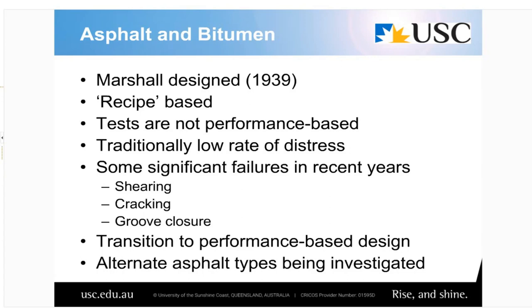It's important, I think, to understand that those shearing, cracking and groove closure issues are very complicated and we don't absolutely understand what's triggering them, but it's likely to be a combination of the increase in aircraft loading, in particular high tire pressures and high individual wheel loads, which would seem to be a trend that we will continue to have to accommodate for some time yet.